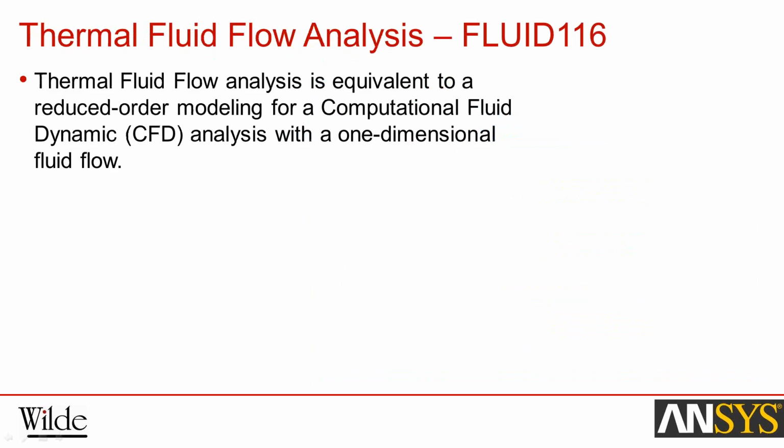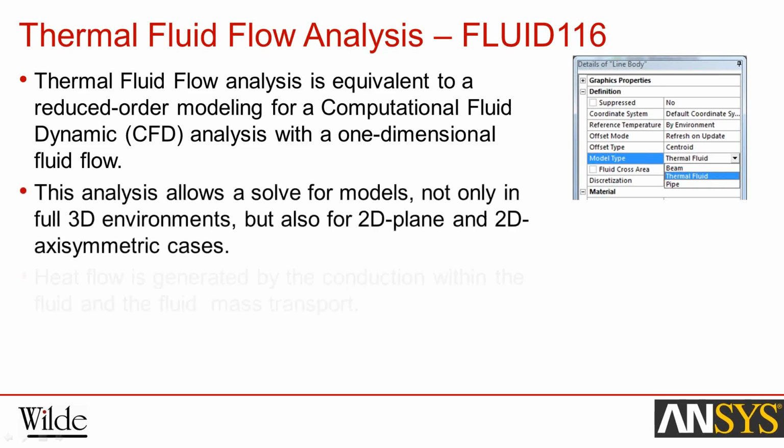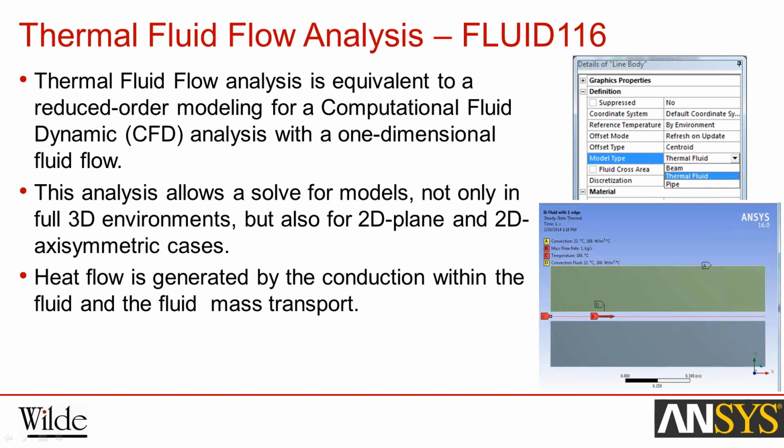The element named Fluid 116 has been available in Mechanical APDL for a few versions, but in version 16 this element is now available from the Workbench GUI. The thermal fluid flow analysis is equivalent to a reduced order modelling for a CFD analysis with a one-dimensional fluid flow. The analysis is able to solve for the 3D and 2D environments, and heat flow is generated by the conduction within the fluid and the fluid mass transport.